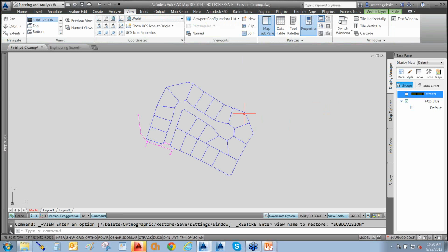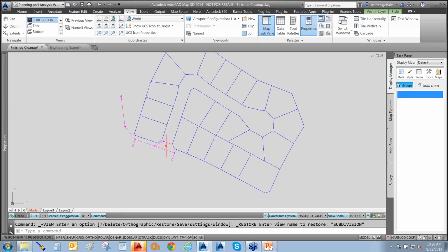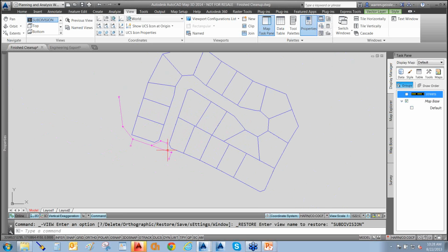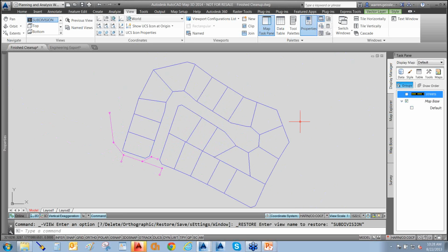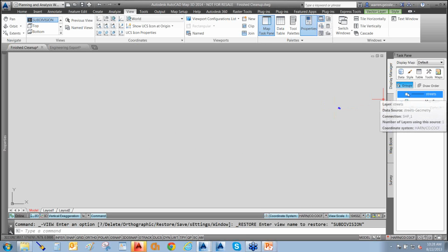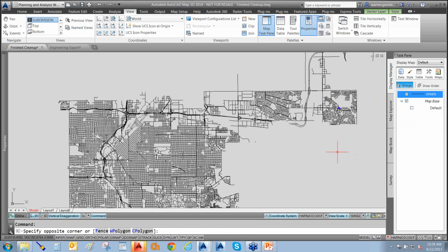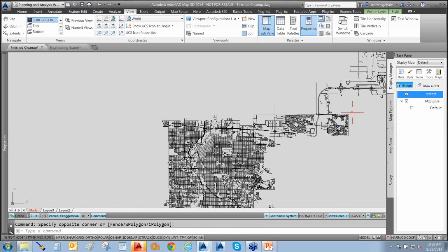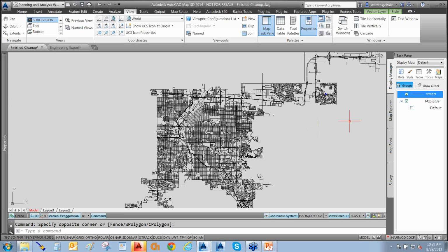Now we've had it set at a proper coordinate system with the proper rotation angle. A moment ago, it was at like 5,000, 5,000 or something. But let's say I had it at a proper coordinate system. Everything's organized. I've cleaned up all the layers. There's my parcels. There's my utilities that I've cleaned up. I've got my blocks. Everybody's on the appropriate layer. And now I can place it, as long as it's in the right location, I can do things like say, okay, bring in all the parcels or all the streets for the entire city of Denver, and I can just lay it right up on top of my parcel. Why? Because it's in a proper coordinate system. I can't stress coordinate systems enough.